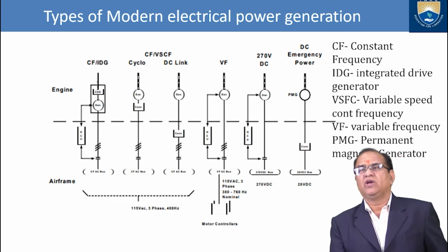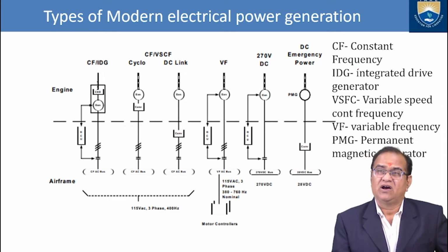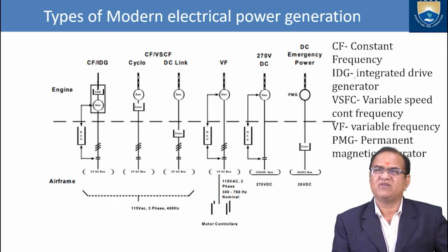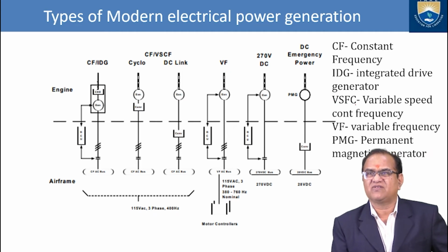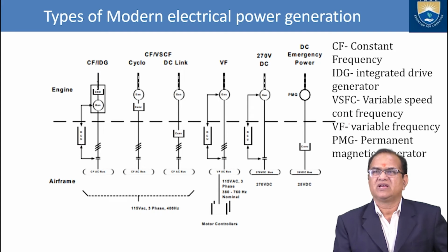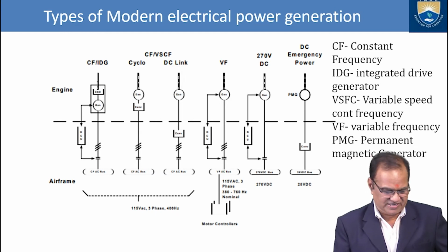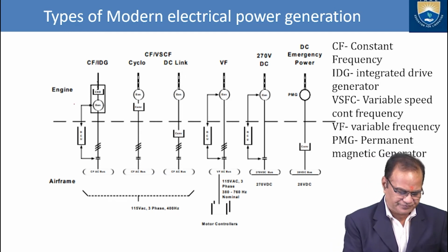So somewhere we want a constant frequency generator, somewhere an IDG, somewhere a variable speed constant frequency generator, and somewhere a variable frequency PMG, permanent magnet generator.